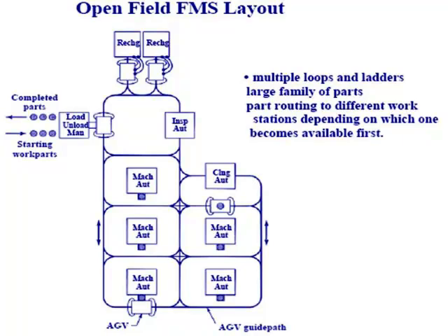Since AGV is used as the primary material handling device, we have to use a robot as a secondary material handling device. Robots will pick the parts from AGVs and place them on the machines. AGVs can move asynchronously in this layout, but other problems like traffic congestion and collision, several problems may arise, and those have to be addressed separately. And this is one layout where a lot of advantages exist. Highly flexible layout.